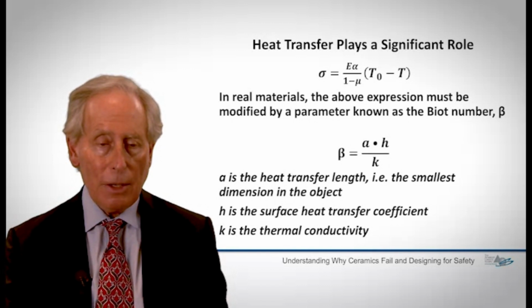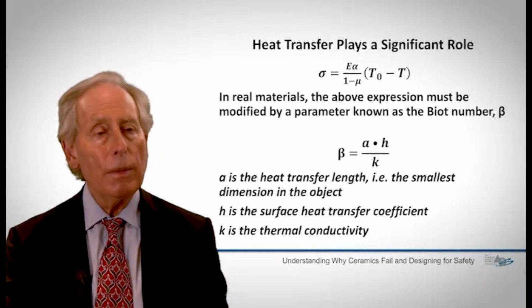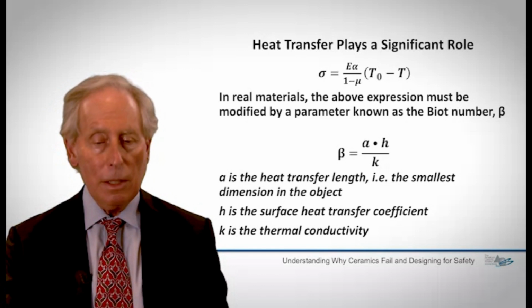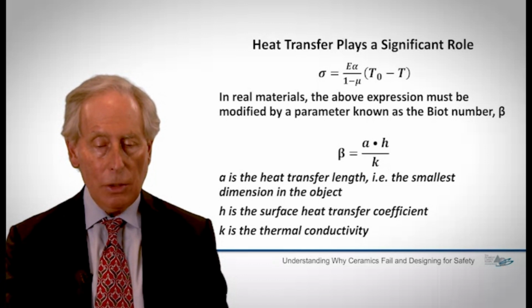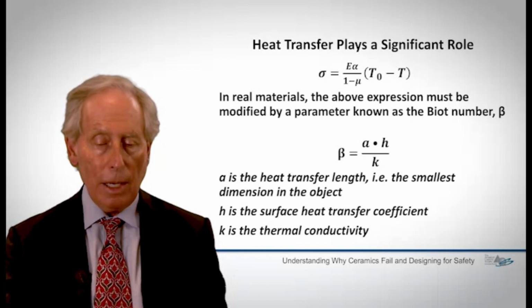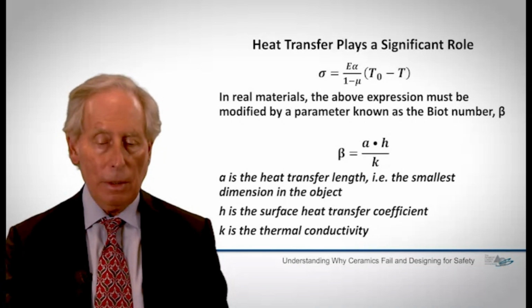So the previous expression really assumed that there would be almost instantaneous heat transfer between the part and the cooling medium, but the actual fact is that you see here, there is another parameter, notice the Biot number, beta, or Biot modulus, which is related to the heat transfer length, the smallest dimension of the specimen that you have, the surface heat transfer coefficient, which is typically very poorly known for most materials, and the thermal conductivity of the material itself.